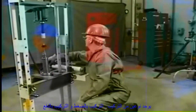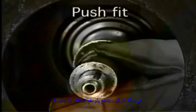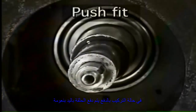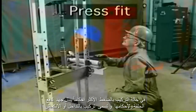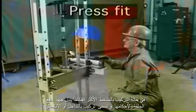There are two kinds of fit, push fit and press fit. A push fit is a fairly loose fit. Usually, a ring that has a push fit can be pushed into place by hand. A press fit is much tighter. More effort is needed to press the ring into place. A press fit is also called an interference fit or a shrink fit.